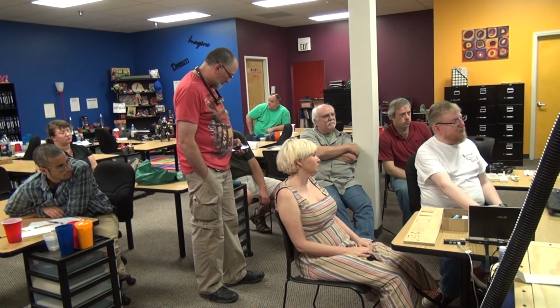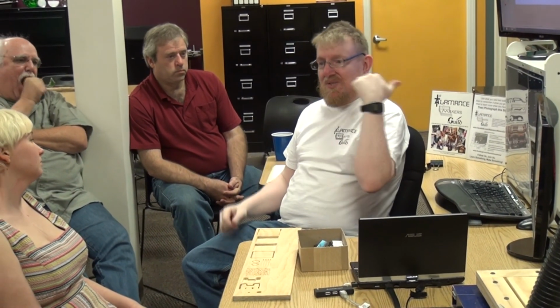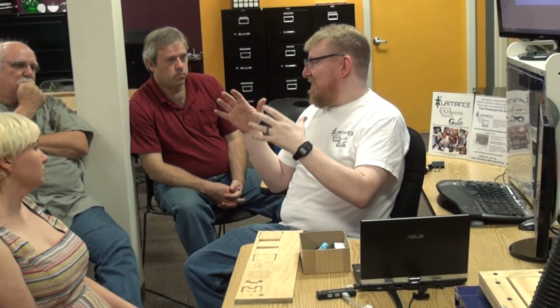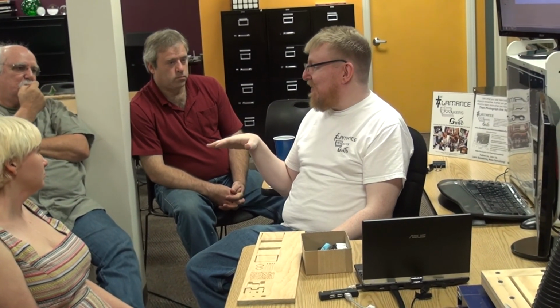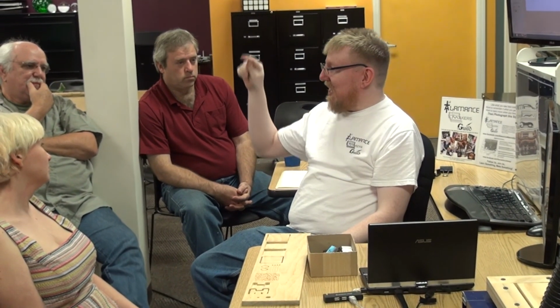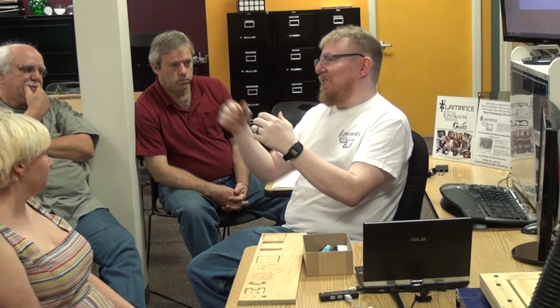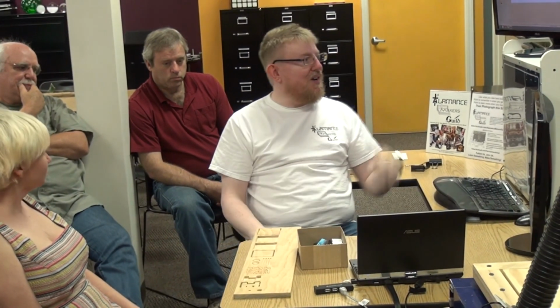You can make allowances. What an allowance is: I designed my part to be exactly 1 inch, but maybe I know it's going to go into an assembly and I need some clearance. So you can build in an allowance, and that way you can work from a geometry in your design that's exactly what you want, but then when you cut it out, you add the tolerances in what you cut out. So if you're familiar with drafting and geometric tolerancing, you would design it exactly the right size, then you put a note about how far off it's allowed to be. Because materials do, well, you would know all about that. So that's the idea, this allows you to do your tolerancing.